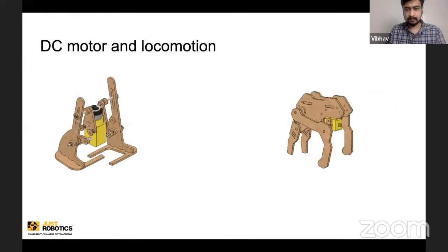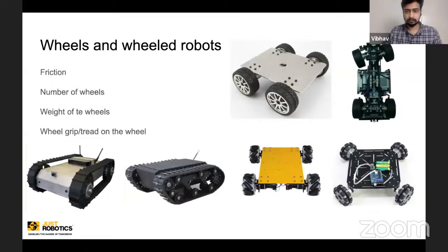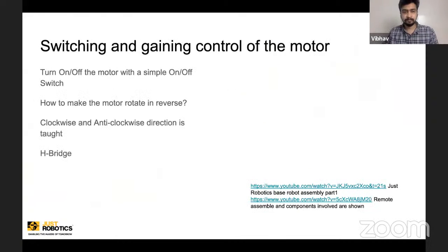So here we have this motor and it is almost like a cycle pedal. You consider this as a cycle pedal. You would have seen a similar mechanism in a railway engine. A 360 motion is converted to a different elliptical motion, which enables the robot to walk. That is the same mechanism that is used here. So there is an offset here. The rotation is now transferred to an offset, and then it is almost like the mechanism of a train engine. That is how I'm converting the rotational motion to the walking mechanism.